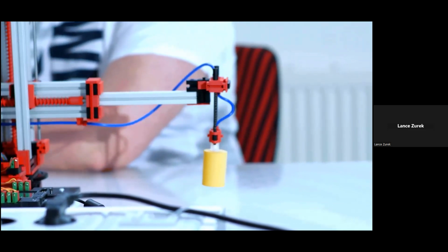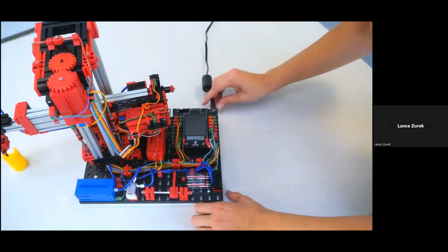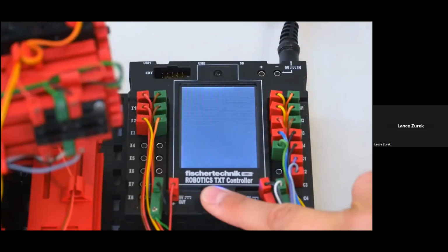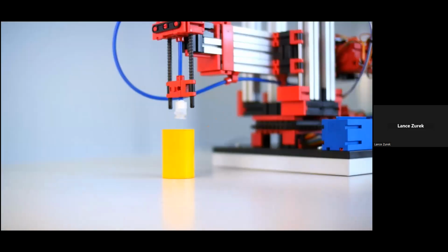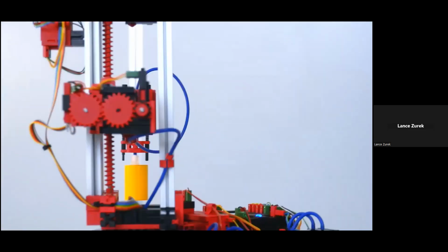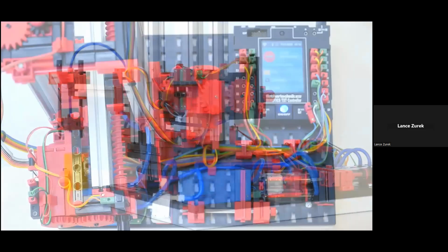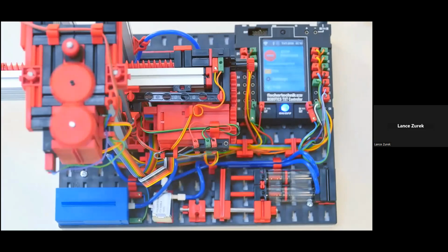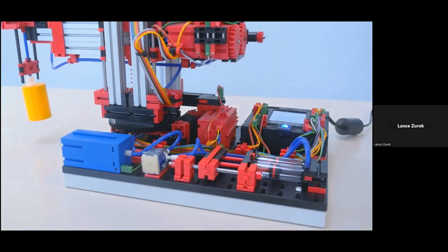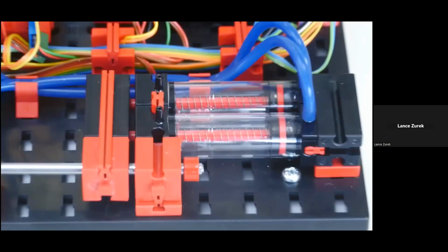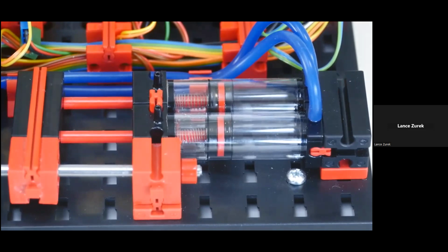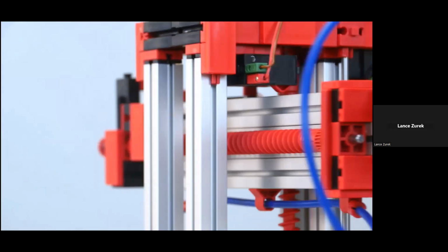The dimensions of this model are approximately 9 by 19 by 15 inches, and it has a weight of about 7 pounds. The 24-volt version of this model, as well as all of the first 5 24-volt models that we're going to be looking at this afternoon, each have a relay board for motor polarity reversal and both a multi-pin connector, in this case 34 pins with a grid of 2.54 millimeters, as well as additional PCB terminals with push-in connections for all inputs and outputs. Again, the 24-volt version of this model, as well as most of the 24-volt versions that we're going to be looking at today, will require you to provide the PLC and the programming.